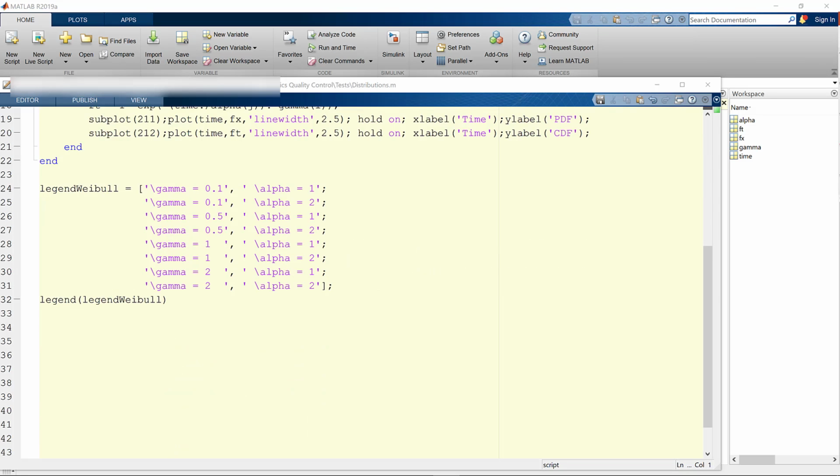A statistics and machine learning toolbox in MATLAB offers several ways to work with Weibull distribution and fit Weibull distribution to data and estimate parameters including scale and shape parameter, mean, and variance. Let's generate a single random number from the Weibull distribution with a scale 2 and shape 2 with a Weibull random number.